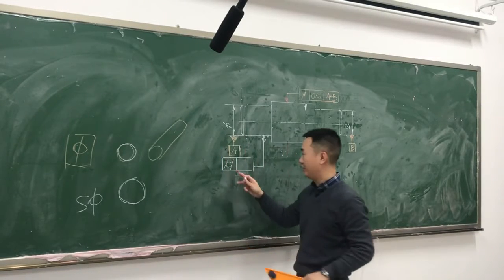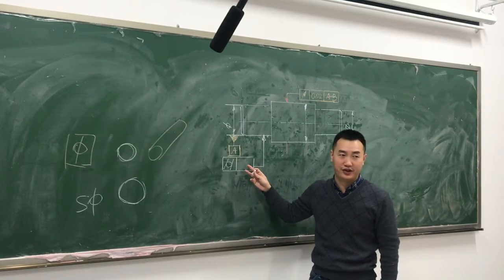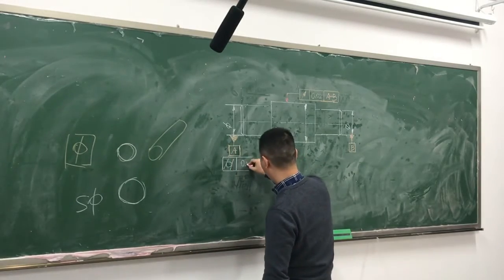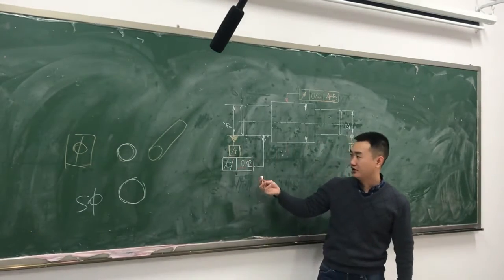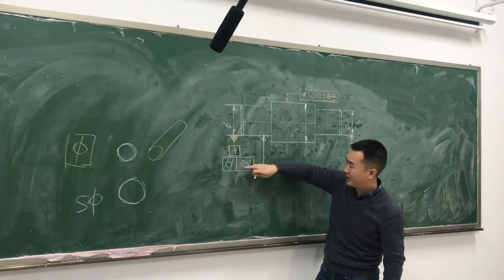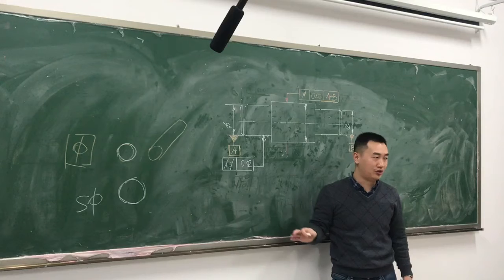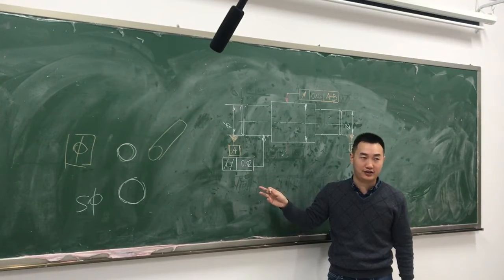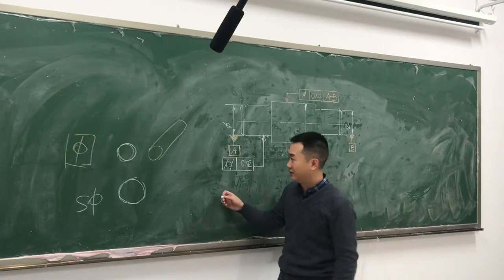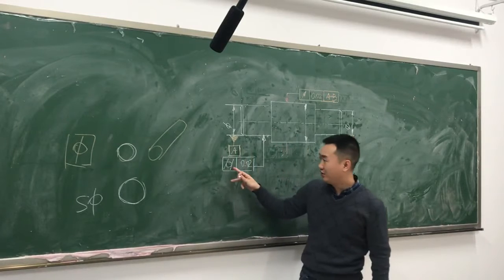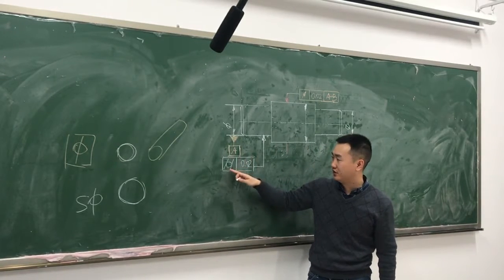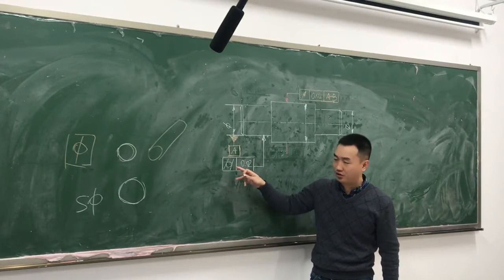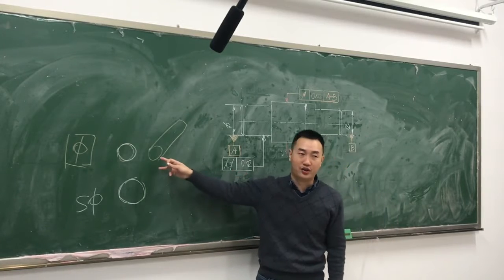So for cylindricity, should we put a phi before the value? Originally it's 0.02. It is measuring cylindricity, so what's the tolerance? You should think about its tolerance zone. What does the tolerance zone look like? Even though this kind of form tolerance is called cylindricity, you should not just think that the tolerance zone will also be a cylinder.